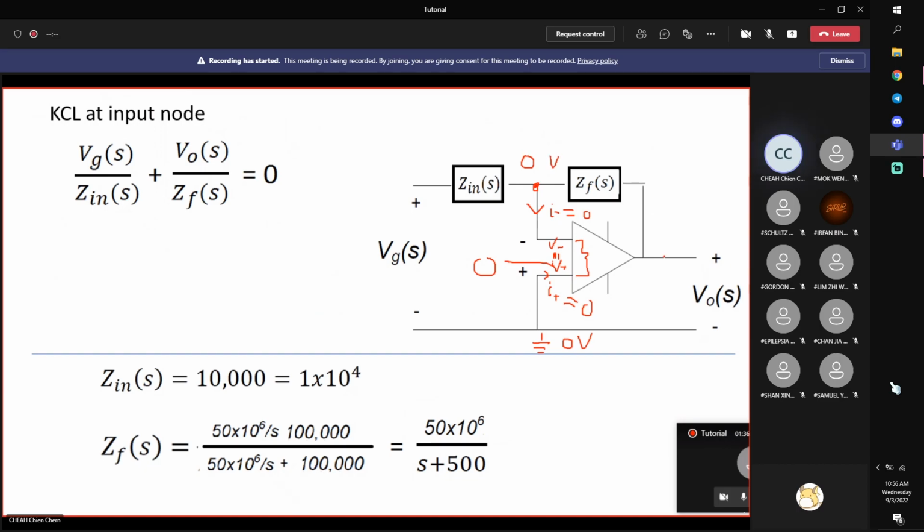That means that the op-amp is basically just telling you that some of the node voltages are equal to some values or in terms of some variables. After that, you can just treat it as if this op-amp is not there anymore by imposing the voltage and current condition due to the op-amp property, and then analyze the circuit.